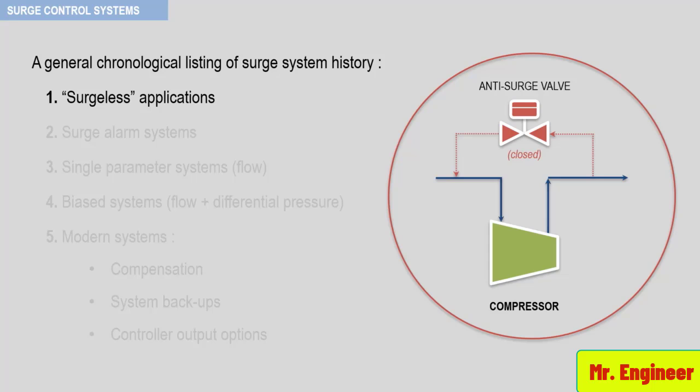The conclusion being that since there are not any variable resistance points in the process system, like valves, coolers or reactors that can foul, then the compressor cannot surge. If the molecular weight and gas inlet temperature are constant and the compressor will not be subjected to mechanical damage or fouling, then this assessment is totally true.